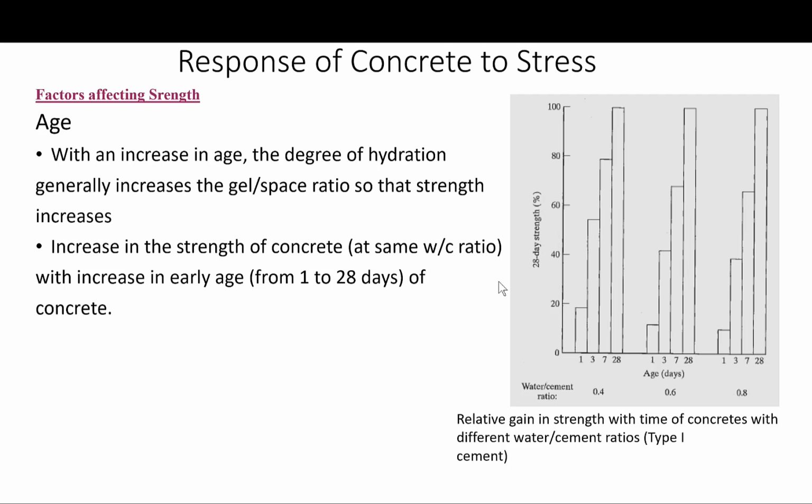Okay, as we pointed out previously, high strength concrete is often designed for strengths at 56 or 91 days to take advantage of the significant increase in strength that occurs following several weeks of curing.